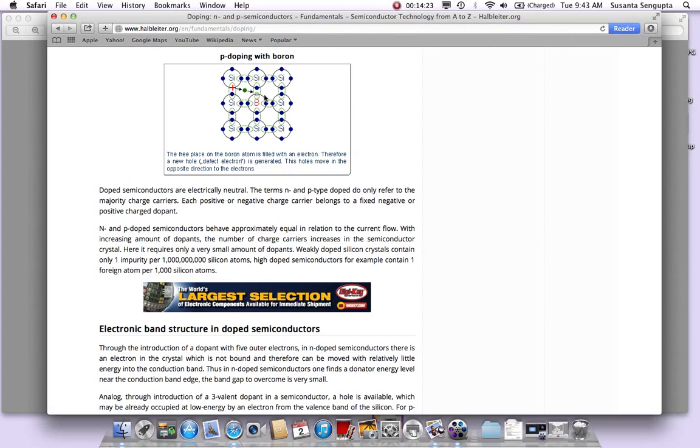But a strong doping is you could do a lot of them, where a lot of these silicon atoms, because this is a continuous lattice, if you extend it, you will see many of these places are going to see a lot and lot of borons, where it could be almost up to 1,000 silicon atoms. That's a very, very heavy amount of doping. So then it will take it into an extremely P++ type doping. So it's not silicon anymore. It's like an extremely highly conductive form of silicon caused because of a lot of this doping of the boron atoms. Okay, so that's a doping dose to explain it's weakly doped or it's strongly doped.